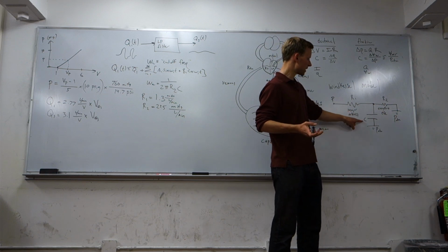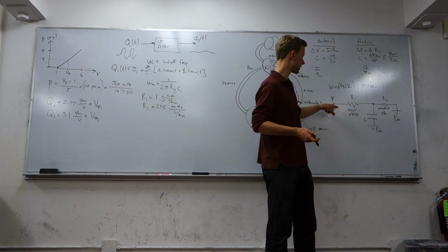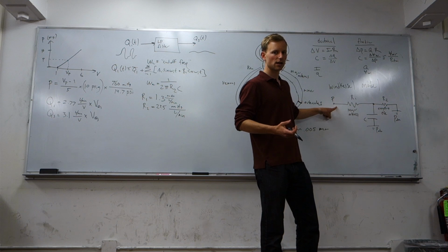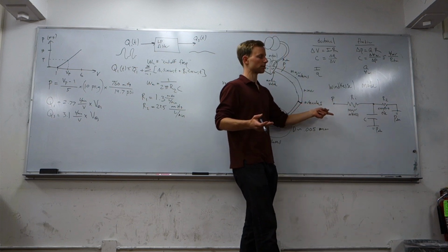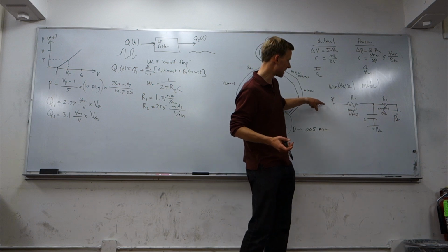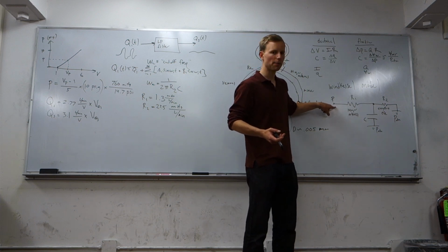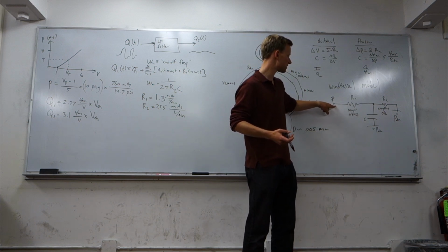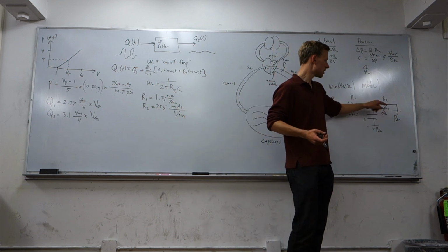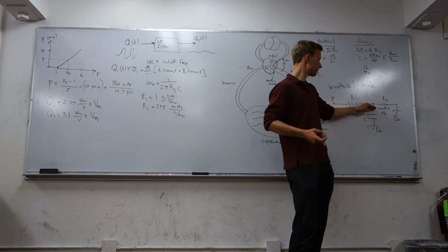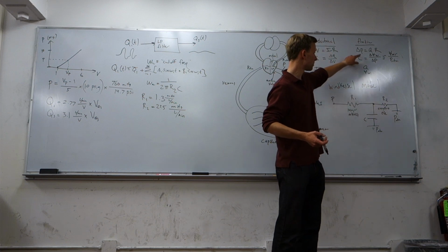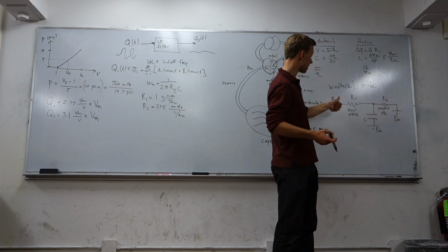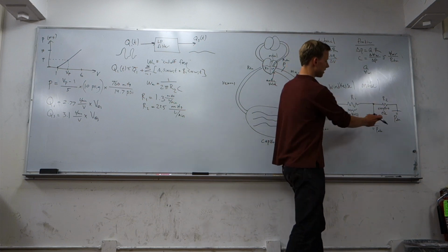But we could also try to negate the effect of the capacitor by inputting a steady state signal, because capacitance only comes into play when you have a time varying potential, voltage or pressure. So we'll send a steady state signal using a steady flow pump that supplies a constant flow rate and a constant pressure through our circuit. The capacitor effect will drop. And the R1 and R2 value we can measure by just measuring the delta P across the whole circuit, from up here down to PATM.